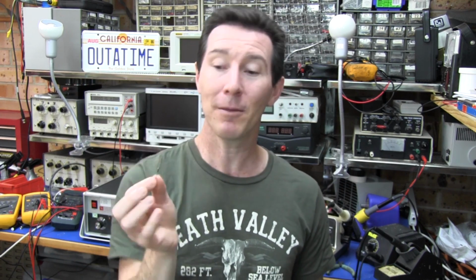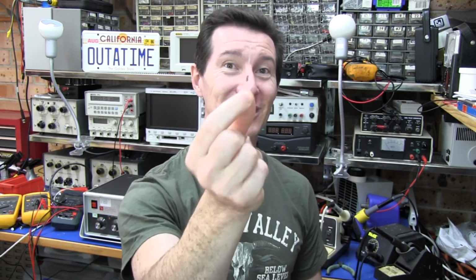If you want 1K and better than 1%, but you've only got 1% resistors, if you put 10K resistors in parallel, you should end up with a better tolerance resistor than that 1%, if it is actually a true bell-shaped Gaussian normal distribution around that center mean value.